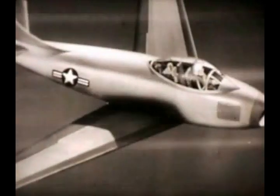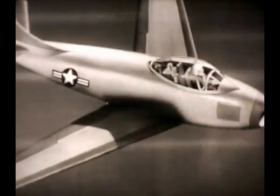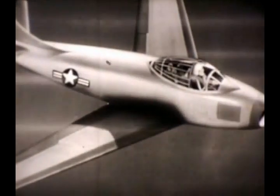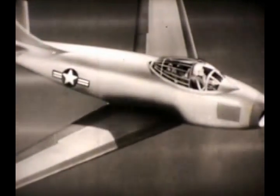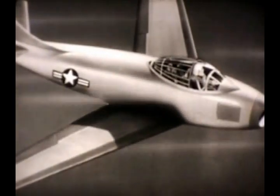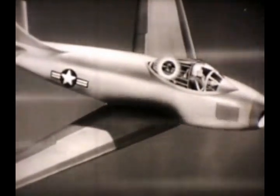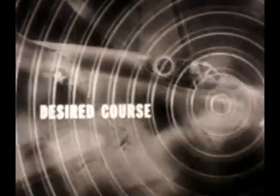In high-speed aircraft, the navigation antennas are usually mounted in the canopy. The sense antenna is molded in the plastic dome and is like a broad wire screen. In some aircraft, the loop antenna is under the dome in back of the pilot. The combined pattern of both antennas is exactly the same as in the old-style exterior mounts.